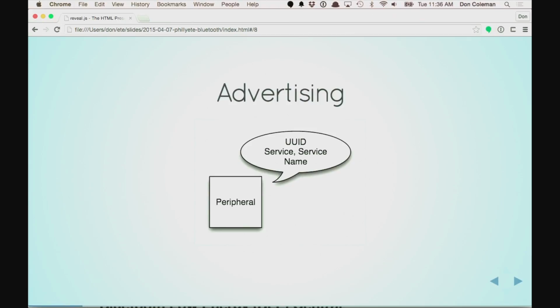So now that we have this service, we need a way to connect to it. With Bluetooth Classic, we would go through a pairing process where it'd say, hey, scan for a device, pair, put in a PIN code, stuff like that. For the most part with Bluetooth Low Energy, the security is called just works. So you do a scan to discover devices, and when you get the devices back, you can connect to them and start working with them. Sometimes you'll get to a characteristic that has an elevated permission on it, and then it will go through what kind of resembles that previous pairing process where you'll need to do something like put a PIN code in to kind of elevate that level of security. But for the most part, when you get started, you can just start connecting and make these things work.